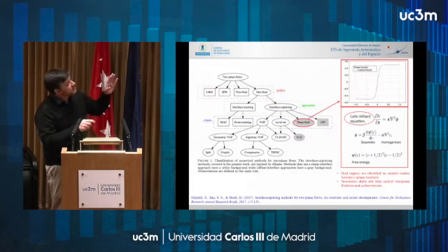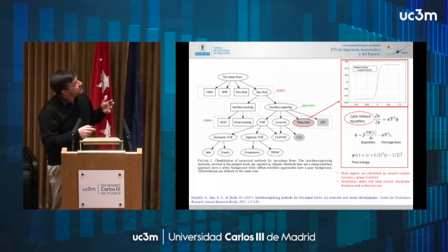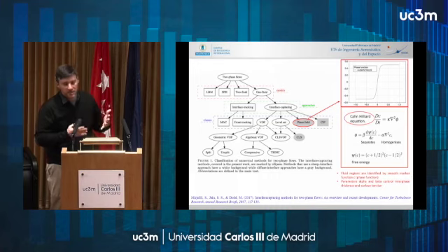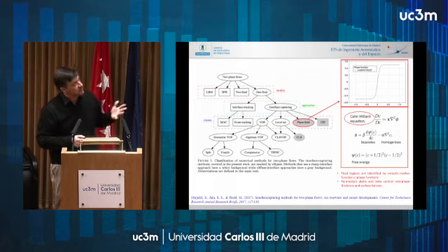Right, so this is taken from a review paper that is down here, where they summarize all the possible ways of computing multi-phase flows. So in particular, of all these methods, you might recognize the VOF, the volume of fluid. This is very classic, level set. We don't choose any of those. We use phase field models. And I'll tell you why. So phase field models require additional equations to be solved, but they can represent the interface between the two fluids, the air and water, for example, as a smooth function. So this is similar to a hyperbolic tangent, right? So it's a function that is differentiable, everything, it's nice.